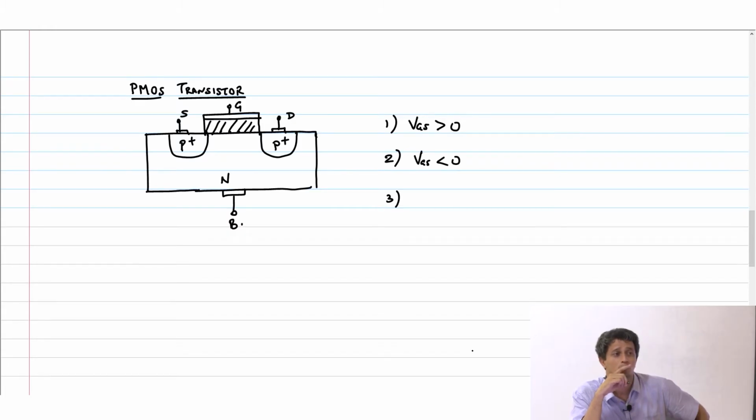You will attract positive charges here, right, and therefore you will get negative charges out here. Enough number of electrons and so on, you will get negative charges there, which is again not very useful. Therefore this region is where you are accumulating more electrons at the surface than what is there in the bulk, and therefore this region is called accumulation.